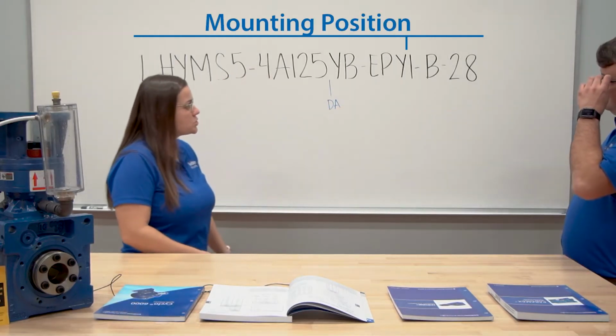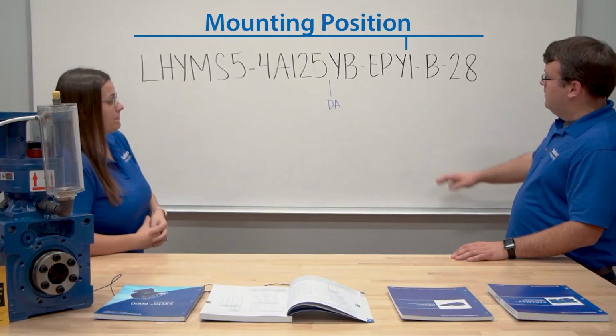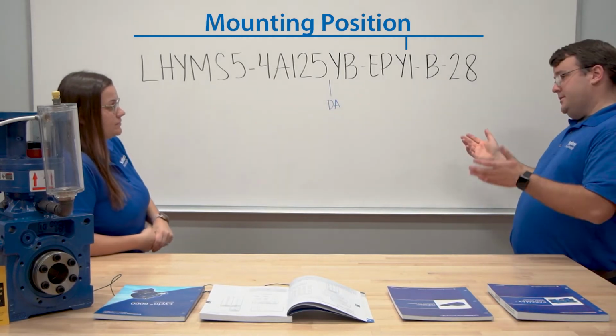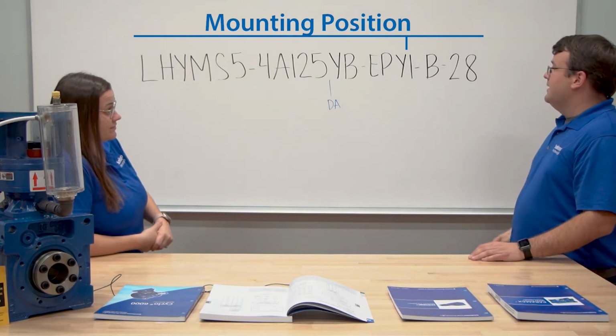After that, you have your mounting position. This is an extremely critical portion of our nomenclature. This tells us how the customer is going to mount the box. It can affect everything from oil levels to where the oil plug is, where the oil gauge is. So that is an extremely important portion of our nomenclature. Y1 and Y3, left, right, horizontal, are probably the most common, but Y2, like we have shown here, and Y4.